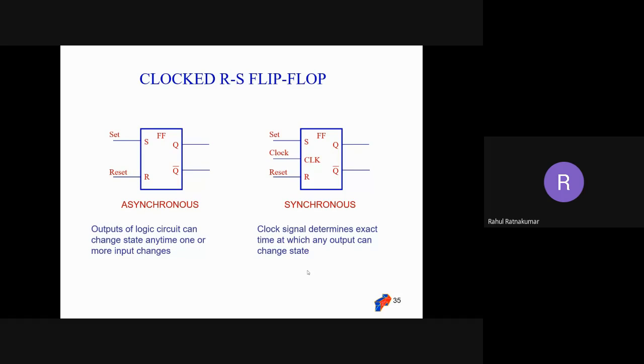So sometimes we don't need to wait for the clock. Let us start the process as soon as it is done. Based on the propagation delay, let me do my process. That is the kind of circuit called asynchronous circuits. I don't wait for the clock. Waiting for the clock is slow, right? Let me do my own processing using handshake signals. When I'm finished, I'll say, okay, I'm finished, let me start the next process. So although it can be a bit complicated, in some circuits it can be very high speed, faster than clocked circuits.